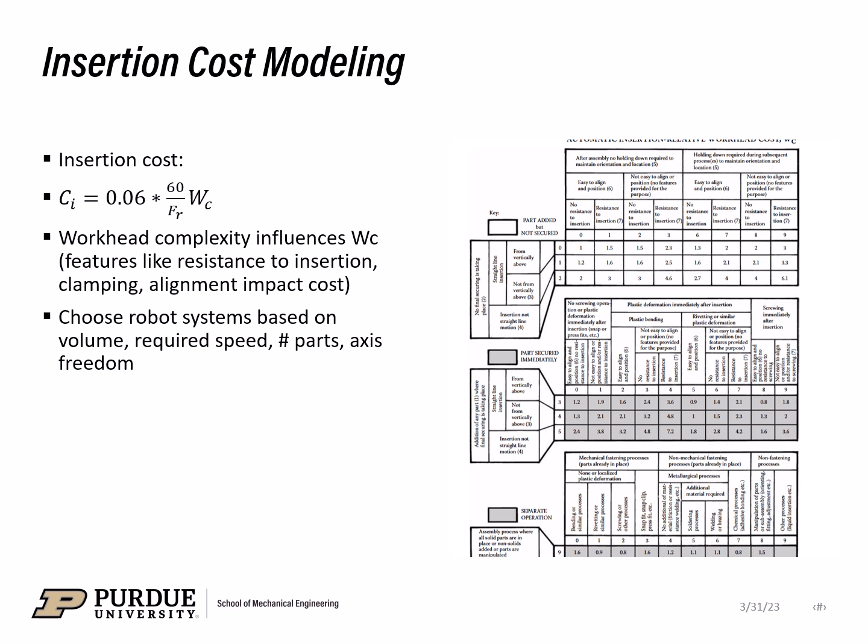So as a design engineer, your responsibility is to always think holistically. For example, does a 2-second cycle time justify the complexity of feeding a non-symmetric part? Could adding a 3-cent feature ultimately save $2 in fixture wear or reduce fault rates by 40%? These questions are really at the heart of design for automation.